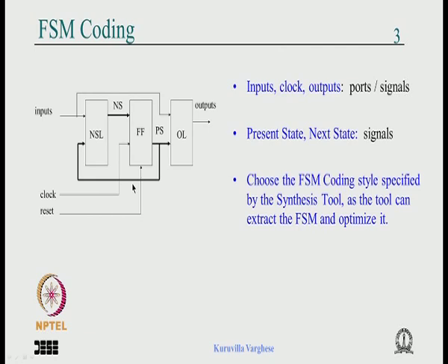An example is the state diagram optimization we talked about. Unless the tool infers that it is a finite state machine, the state diagram optimization cannot be done. There will be redundant states, unnecessarily wasting area in the next state logic and output logic and so on.